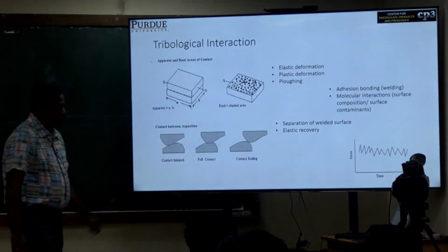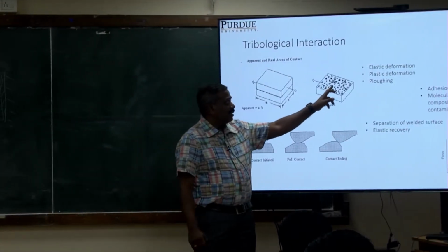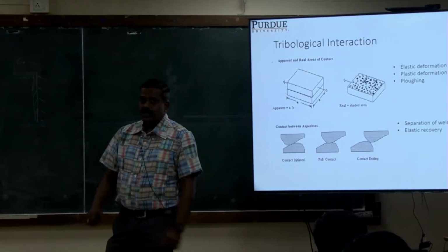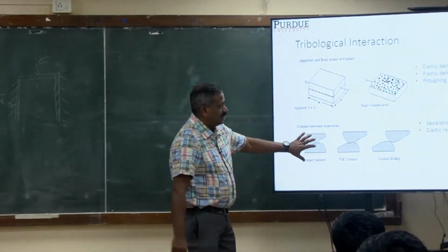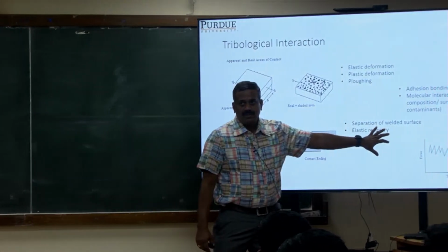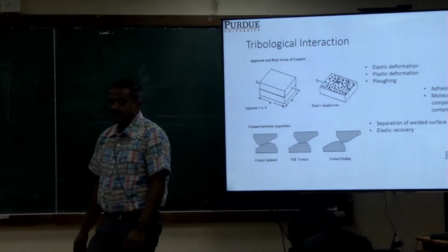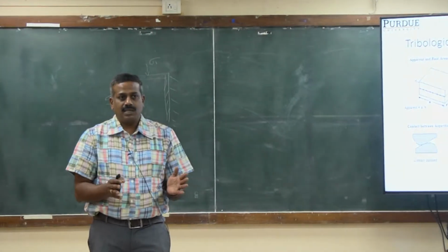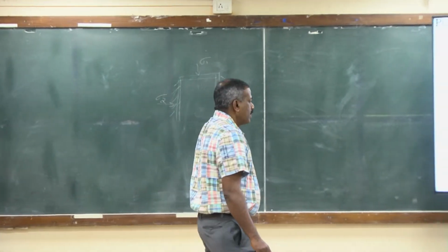So what happens is, when one surface, for example, one contact on this solid and one contact on this solid, comes in close contact during movement, it initiates a contact, and there might be different phenomena occurring while it's moving, okay? It starts from elastic deformation, right? If the normal force is not very high, it goes along with elastic deformation, okay?